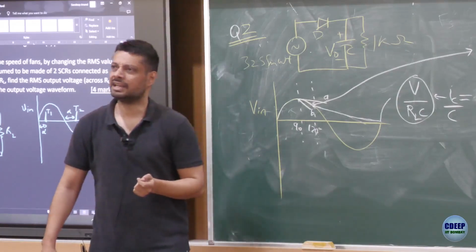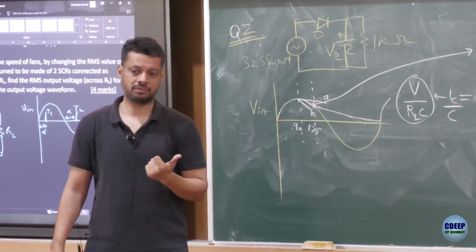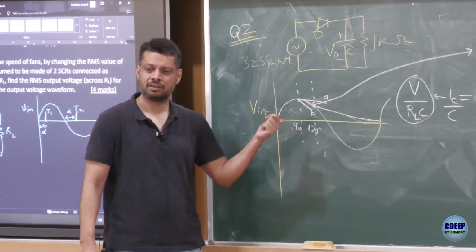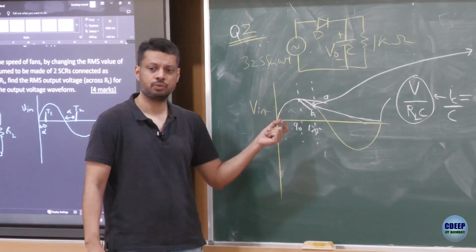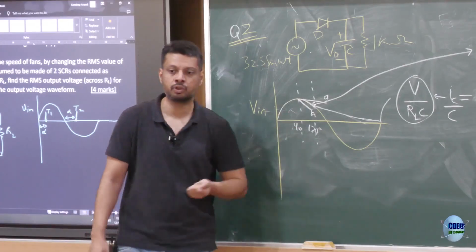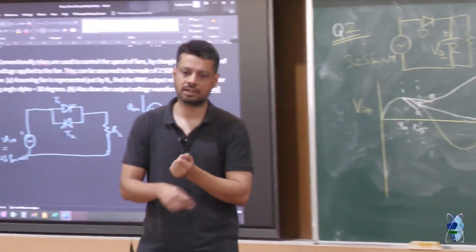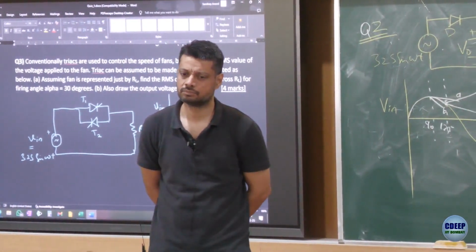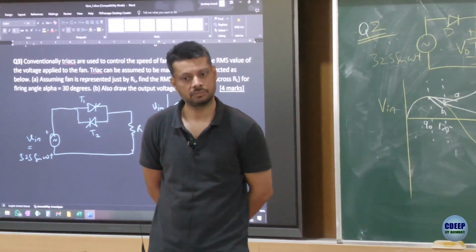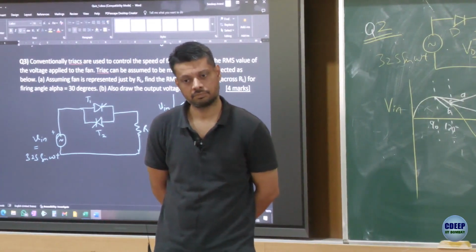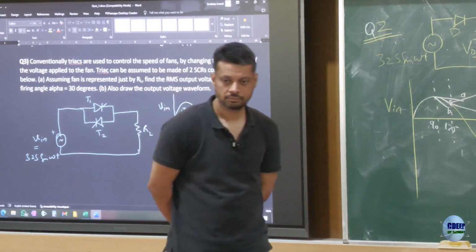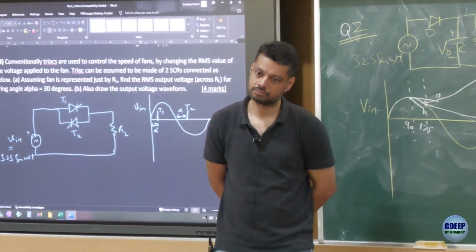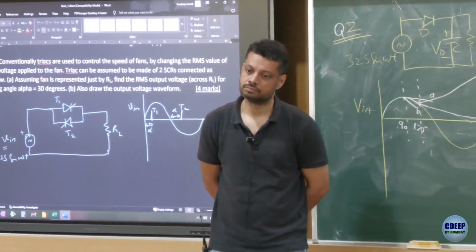And the derivative is continuous, right? Even if you find the second derivative, it is smooth, right? So, can't that be used to make sure that at this point both the derivatives are equal? The actual waveform follows the sinusoid till 120 degrees. Correct. And then from that point discharge starts with exponential decay. So how is the slope of that exponential decay equal to the sinusoidal slope? Because I think it's non-differentiable.